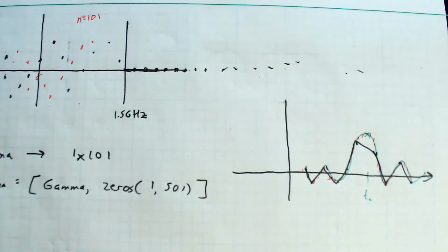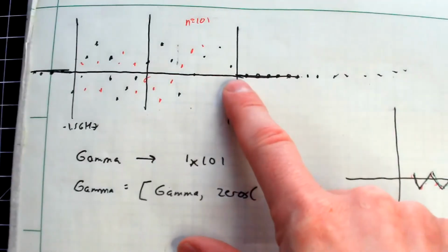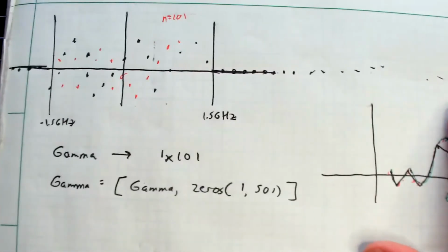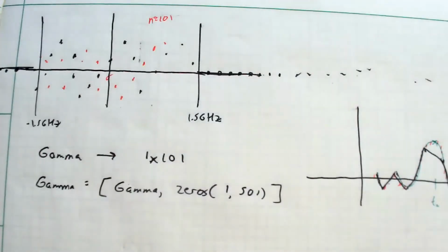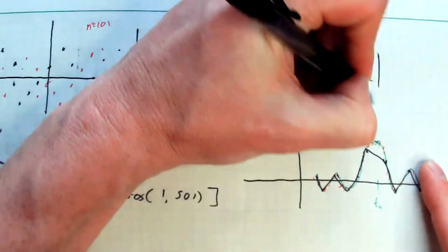function. Now, using this trick, you haven't recovered any data that exists above 1.5 gigahertz. You've only increased the resolution of the output. Yep, that's all you fundamentally did. As far as the Fourier transform is concerned, those zeros were already there. You just didn't sample them. That kind of makes sense. So what that does is essentially artificially inflate your bandwidth all the way out to like 10 gigahertz here.